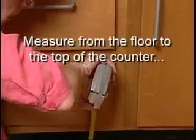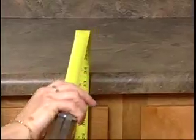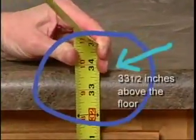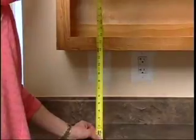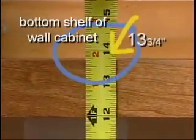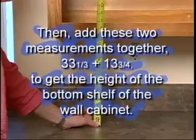Measure from the floor to the top of the counter, then measure from the top of the counter to the bottom shelf of the wall cabinet. Then add these two measurements together to get the height of the bottom shelf of the wall cabinet.